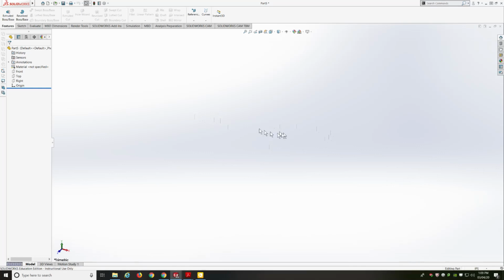All right, so we got to start a brand new part. If you haven't already, go ahead up to the little paper icon and start a new part. And we're going to have a series of sketches here. So the first sketch is going to be on the top plane.